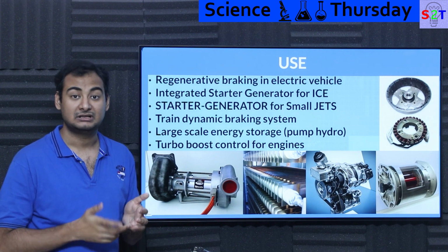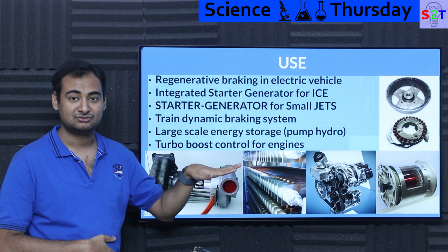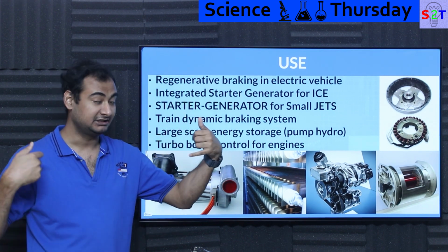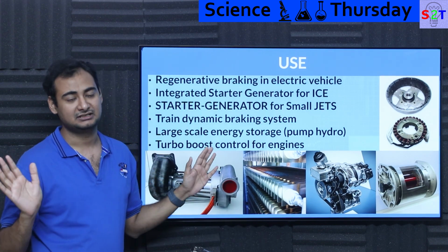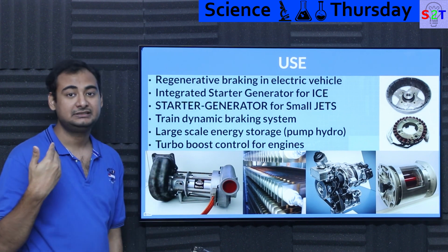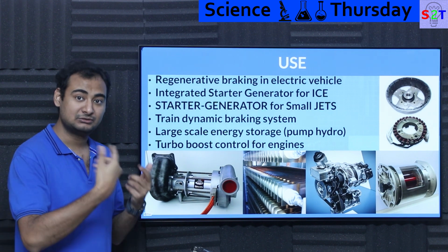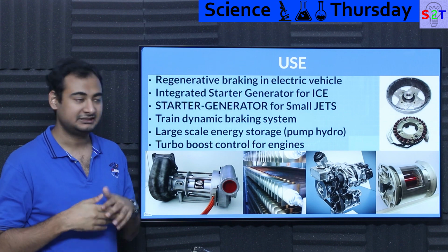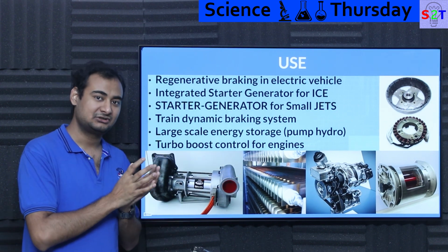Now why would you want to do that? Same thing, if your train is traveling at, let's say, 50 kmph and you want to drop it down to 25 kmph, your brake pads, like brake shoes, those things, will wear very quickly. However, if you want to drop from 25 to 0, brake pads, brake shoes are like, I got this. So the same thing is done. Basically inherently converting the inertia into heat energy and doing it through the motors, you do not have wear and tear on the things that do have wear and tear. There is no wear and tear utilizing this resistor braking. And they generally have a fan that is also coupled with that output.